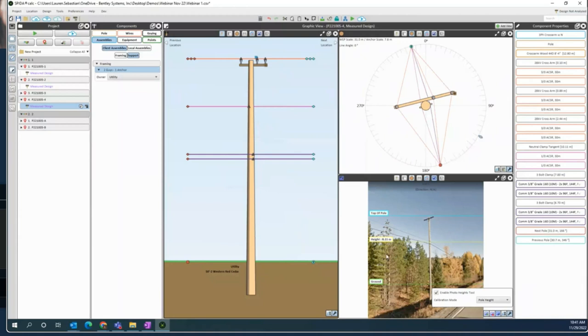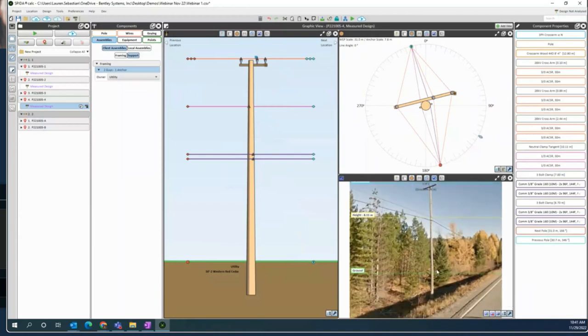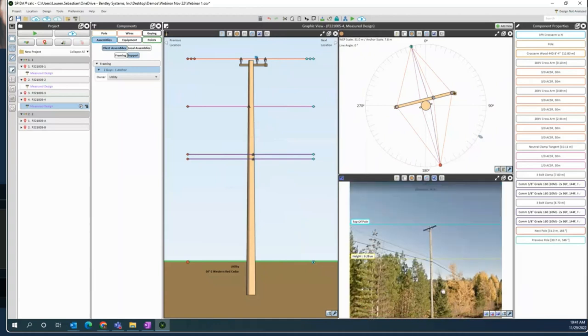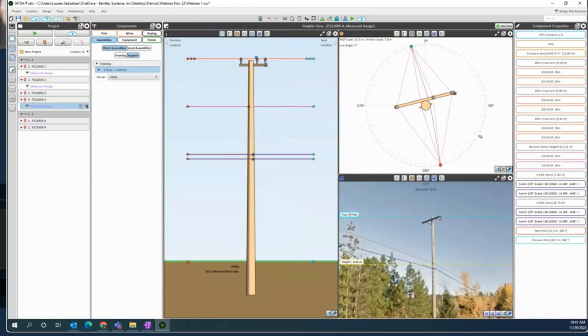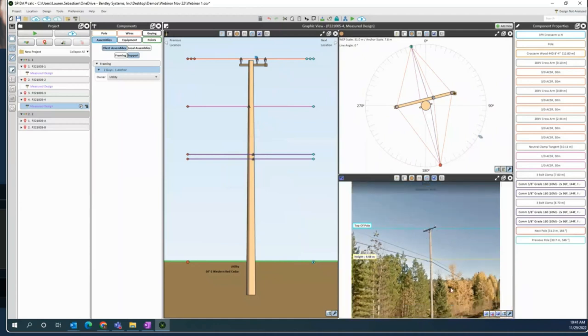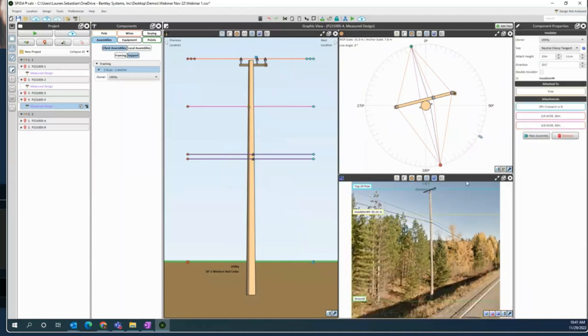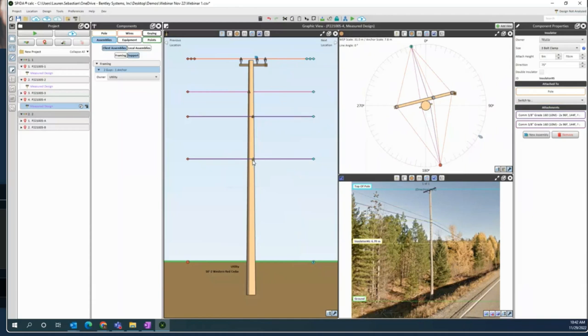So this is assuming that our pole height is a known entity. And I can zoom in on this so that I can accurately try and set the ground and pole top of my pole. And from here, as I select individual components, I can drag in this photo tool to set the height accordingly on my model. This can become a convenient way to get an estimation of what I have in the field and quickly tweak preset framings that might not be exact in the field.